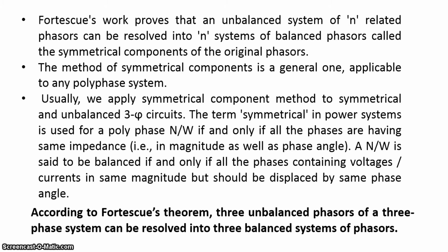Fortescue's work proves that an unbalanced system of n related phasors can be resolved into n systems of balanced phasors called the symmetrical components of the original phasors. The method of symmetrical components is a general one, applicable to any polyphase system. Usually, we apply the symmetrical component method to symmetrical and unbalanced three-phase circuits.